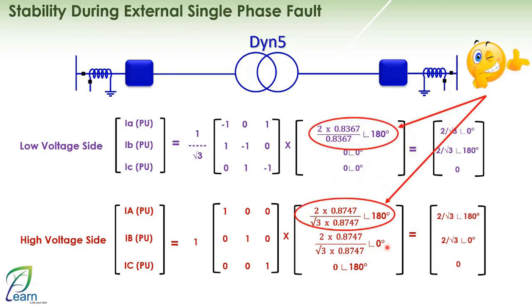And here we will address something very important. Some people make a mistake by saying, I have a tester and I start working with it, injecting with it. And then, to represent the differential state, they take it generally and apply it incorrectly on the transformer. They say, inject phase red on the high side and phase red on the low side with an angle of 0 and 180, which gives me stability, and I start changing the amount of current until I reach the trip stage. Of course, this is wrong. Why? Because they always think that 0 and 180 will give them the stability condition.